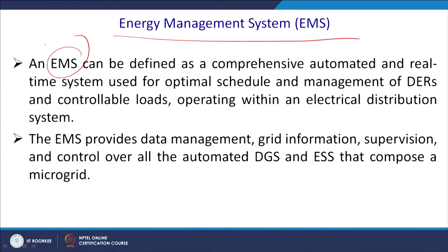So, an EMS, that is energy management system, can be defined as a comprehensive, automated, real time system, no one does it, no human being, but you can employ human beings as options, but it is generally automated, used for the optimal scheduling and management of the DERs and controllable loads operating within the electrical distribution system.